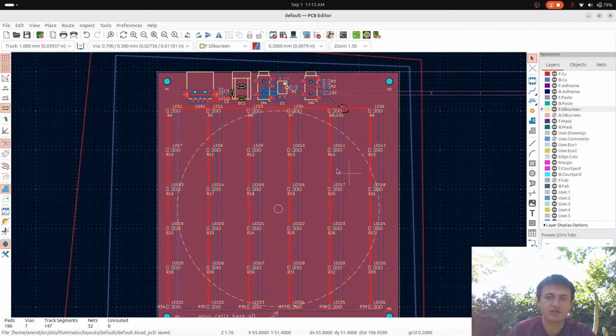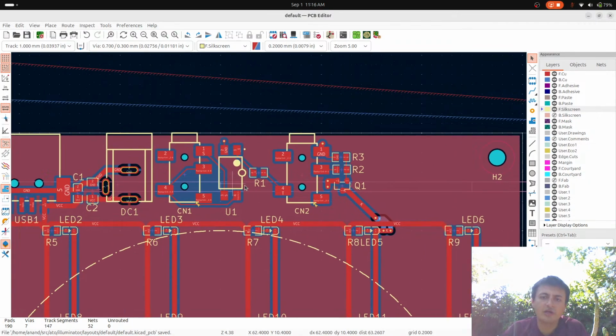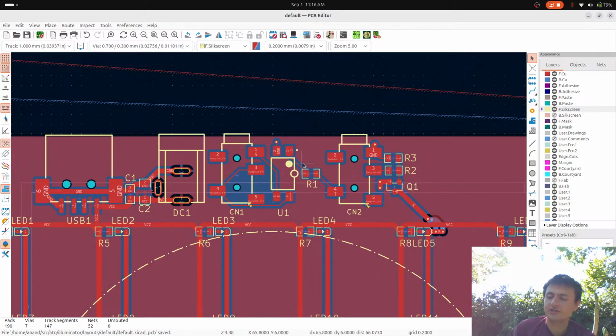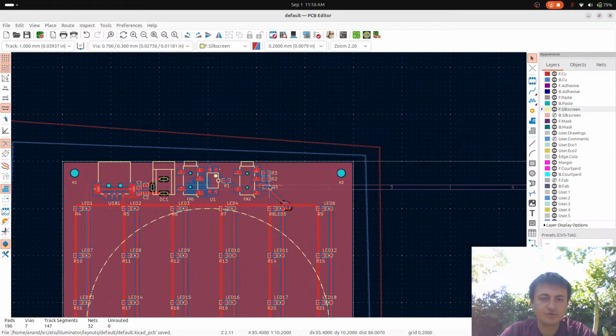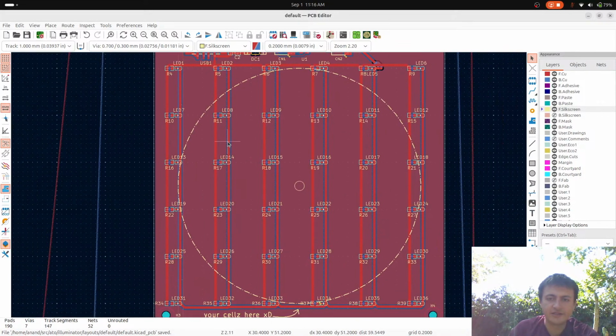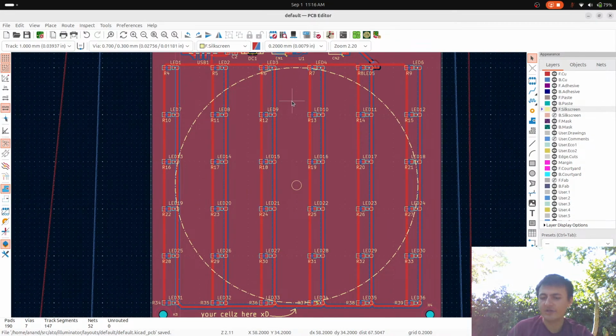And basically, it's a grid of LEDs, an optocoupler, and a MOSFET. The optocoupler is for controlling basically a port on the camera that lets you take pictures with a button. And instead of a button, we were just using an optocoupler and a Raspberry Pi Pico. And we have a MOSFET to turn on the LEDs. And the nice thing about this is that if in the event we end up engineering cells with a different color protein, we can just use another color, and this should work all the same.